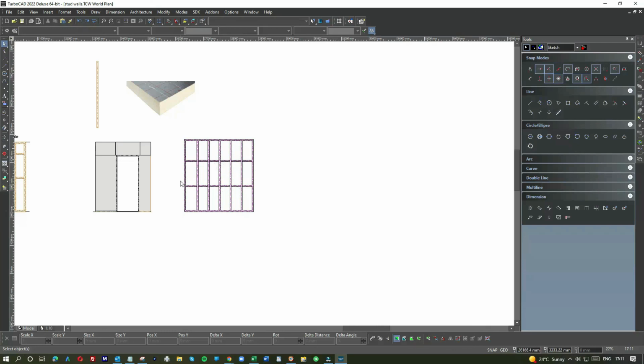Do it by bricks. Don't just do it on top of each other and keeping the line. So what we're trying to avoid is one complete line floor to ceiling with plasterboard, where the plasterboard meets. So you go up, you go across, and that's going to make a much stronger finish when you do it like that. Okay, you've done your first stud wall.